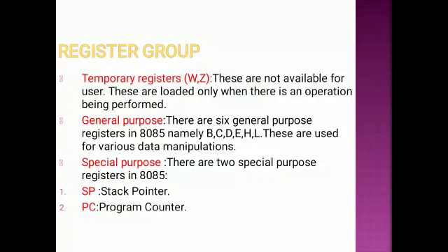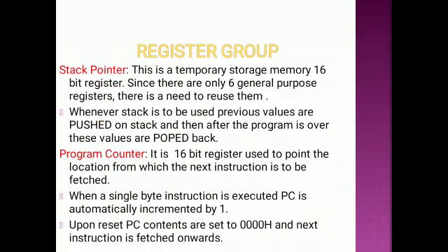General purpose registers: 6 general purpose registers having data storage capacity of 8-bit. Special purpose registers are 2. One is the stack pointer, another is the program counter. Both the special purpose registers have 16-bit data storage capacity. Stack pointer is a 16-bit register.